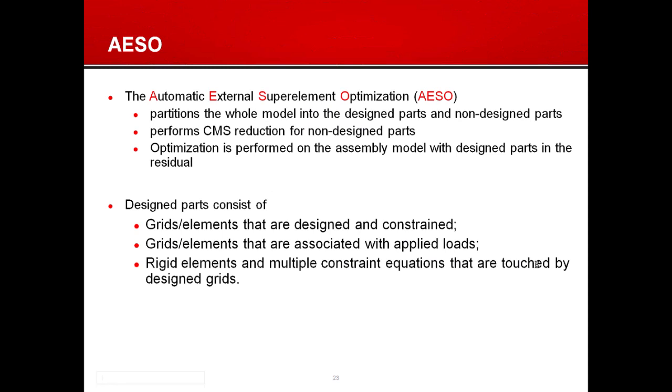One other method allowed in Nastran is called automatic external superelement optimization, AESO, and that builds up on our superelement technology, where the non-design model is reduced, statically or dynamically reduced, and a component mode reduction process is used.